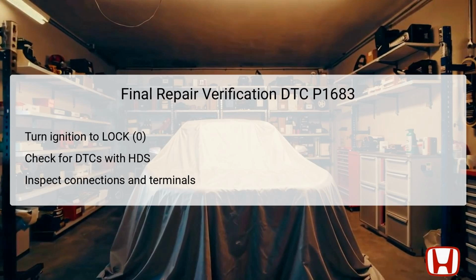In the event that DTC P1683 is indicated again, it is essential to check for poor connections or loose terminals at both the throttle body and the powertrain control module, PCM. These connections must be examined and secured to prevent future failures and ensure effective communication between components.